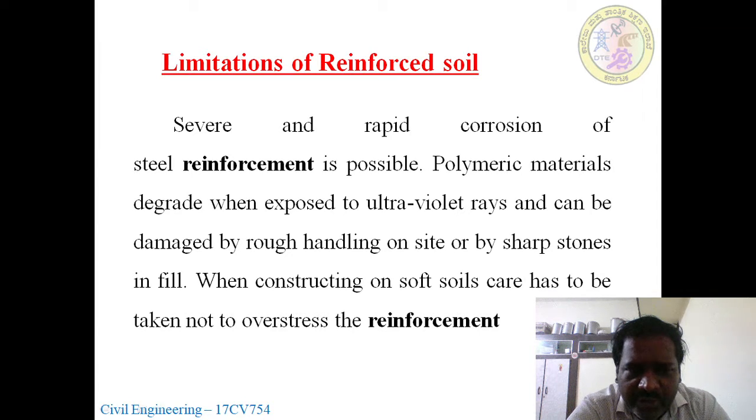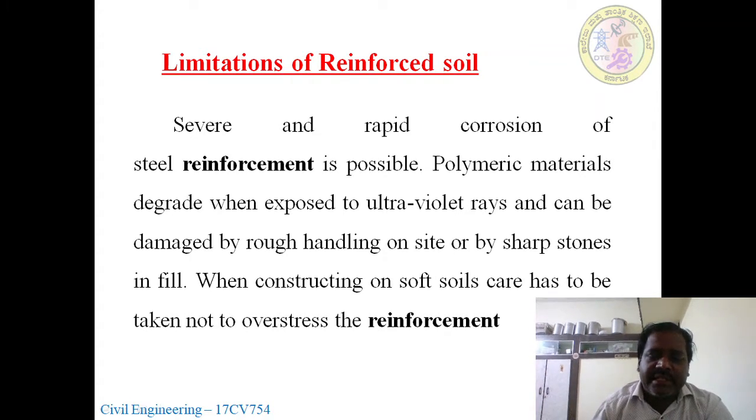It should not come in contact with sharp stones. When constructing on soft soil, care has to be taken not to overstress the reinforcement. Where soft soil is there, we have to take care about the reinforcement, as there will be overstress.